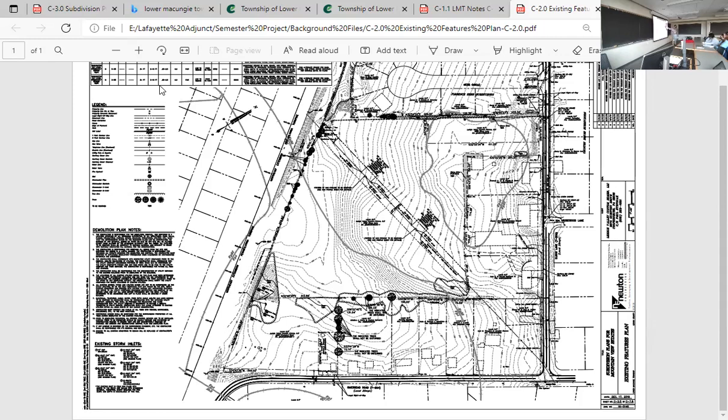Right, somebody said it, it's the highest point on the ground. So to get the stormwater to it, you'd have to pump. Do we want to pump stormwater? Nope, this isn't New Orleans. It's probably not a good idea, because of the expense, and because with a little bit of logical design, we could put it where it should go. How about down here? It's better, but it's not right there, right in the low spot. That makes the most sense.